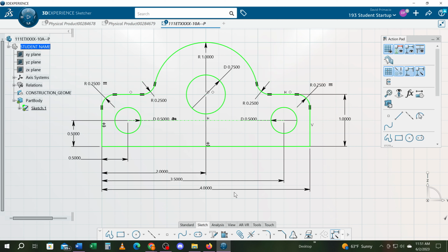In this example, I'm going to try and explain why this method is a poor technique. If this were like a plug-in, you'd want all these holes to line up so that whatever's going into it is going to fit. With this dimensioning, the tolerance is going to create a situation where the parts are not going to mate if they go to the minimum or maximum conditions of the tolerances. So let me try and further explain that.